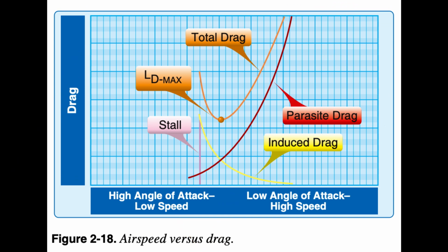Thrust required for increases in speed. Above the lowest total drag airspeed, Figure 2.18, faster speeds, lower angles of attack, for level and climbing flight require greater thrust because of the increased drag created from the faster speeds. AOA is the primary control of increasing and decreasing speeds, and increasing thrust generally does not produce higher speeds, but additional thrust is required to maintain level flight at higher speeds.